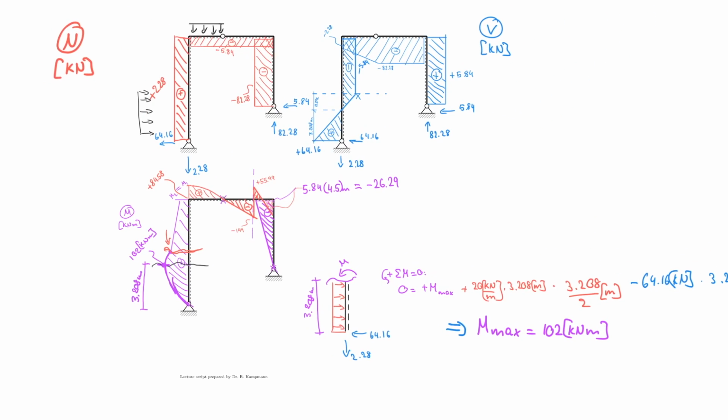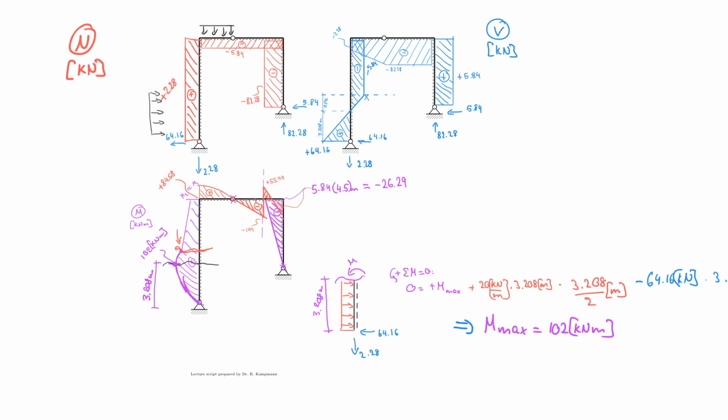But let's review this real quick. So now we have drawn for the first time the internal force diagrams for a rectangular frame: normal force, shear force, and moment. And as we did before, we used our same logic. So for example, for the normal force, tension and compression is important, and it defines our positive and negative values. If nothing changes, then it's just constant, and that's mostly the case for us in this class. And we were able to follow that logic here.